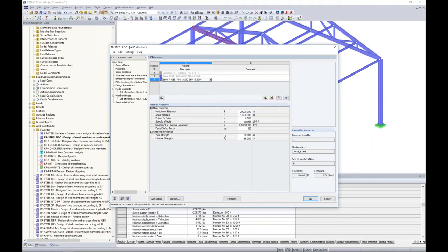Now, this is now recognized in the 2016 spec as an approved HSS material, as I mentioned before. With 1085 and 1065, these have more stringent wall tolerances than the previous A500. So what this means is that the code tells us we can now use the full nominal wall thickness for design. This is in comparison to the A500 where we had to use 93% of the thickness.